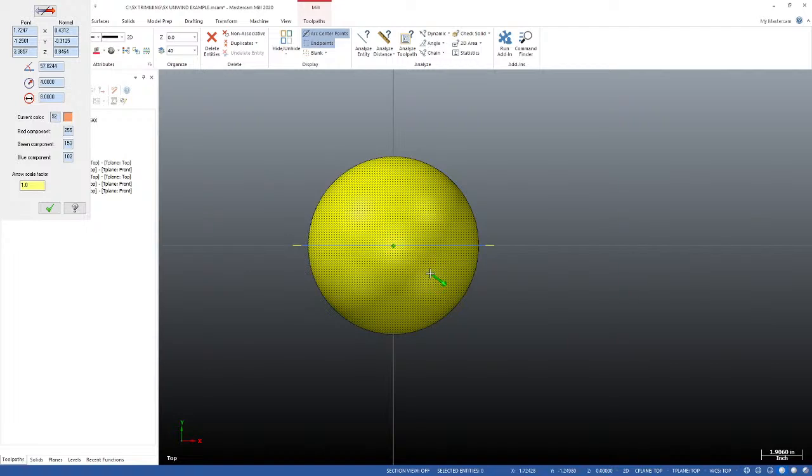We're also on a 4-inch radius hemisphere. So this is a compound angle if we look at it in terms of machine output, right? So if I put a vector exactly there on my part and used a surface normal line that was exactly perpendicular to the surface at that point, I would use that normal vector in a machine matrix to resolve my A and C or B and C angle values.